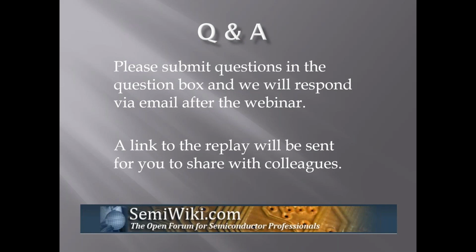Final question, is EPD detection required for processes such as ALD and ALE? Yeah, that is an excellent question, Dan. Many people mistakenly think that the self-limiting nature of the ALD and ALE processes makes them very safe and not prone to process drift and shift. This comes from the belief that these techniques are truly one layer at a time. This is not strictly true. Rather, they have a characteristic removal or deposition amount per cycle, which can be a little bit more than a layer or a little bit less.